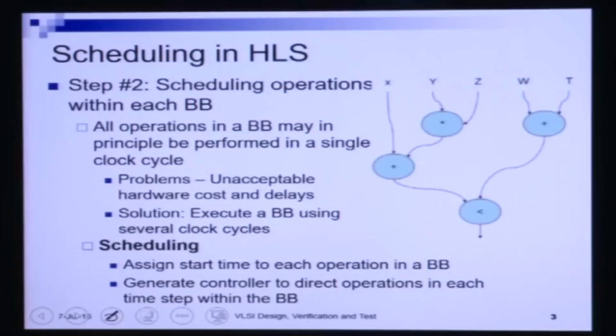So, therefore, to obtain the complete master controller, we need to ascribe timing to operations within a basic block, and timing to operations within a basic block is done through scheduling. So, next we have now arrived within a basic block, and we have to schedule operations within a basic block. Now, before going into scheduling, we also said this before that all operations within a basic block can ideally be scheduled in a single clock cycle. However, if we do so, then there will be unacceptable hardware cost and delays.